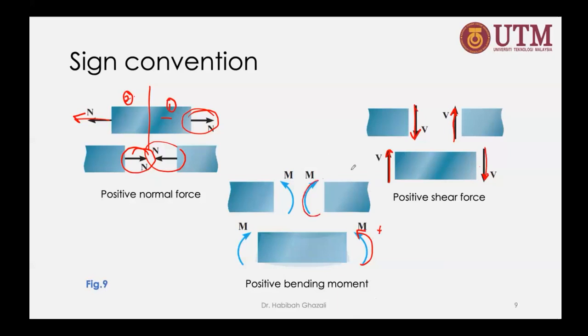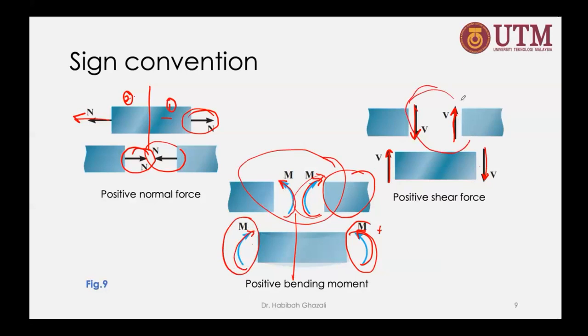For internal forces, in this section it's going to be positive if it's going this way, because it is resisting this force here. The same with this section: the concentrated moment is going that way, and the internal force is going to resist that. So this is positive, this is positive, this is positive for internal forces.